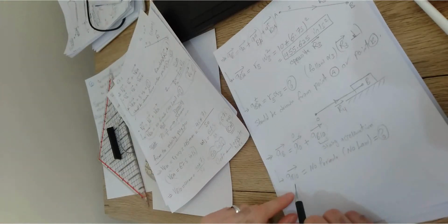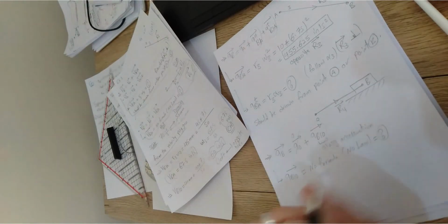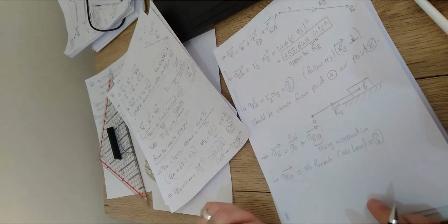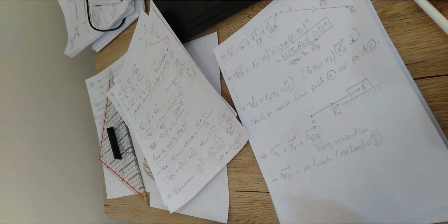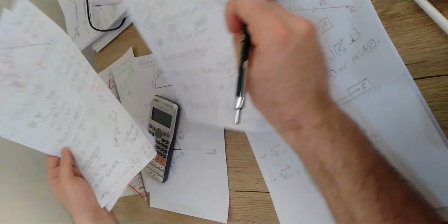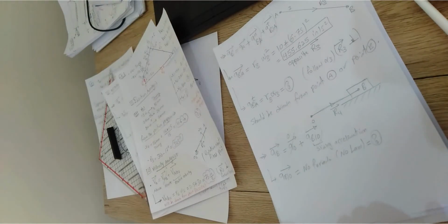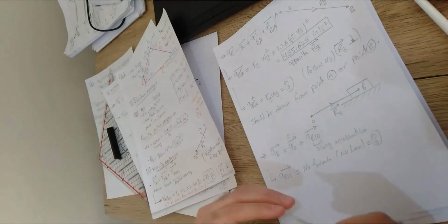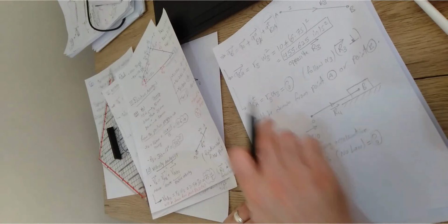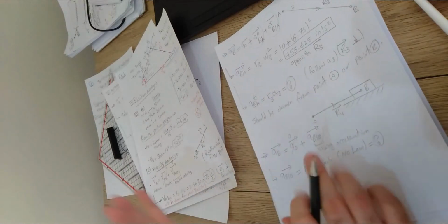So in this case automatically the AB relative to O will be given, and you're going to plug the value here. But in this example, this sliding acceleration is not given, so it means that it will be the second unknown. And as you remember, in the acceleration analysis, we are limited to just two unknowns, which are these two unknowns here that we are seeking their values.